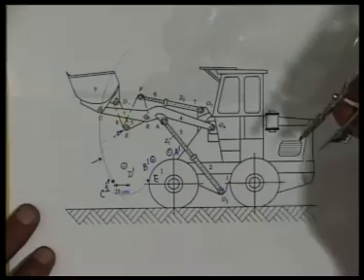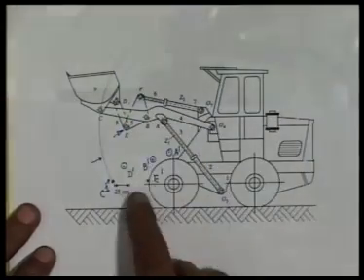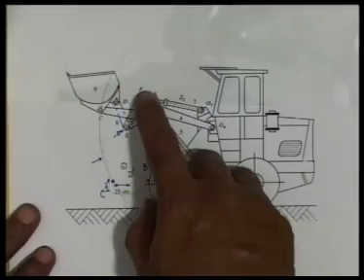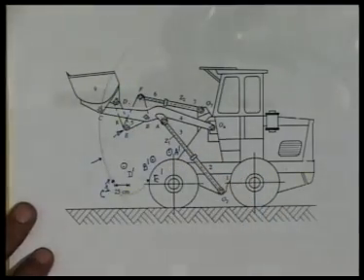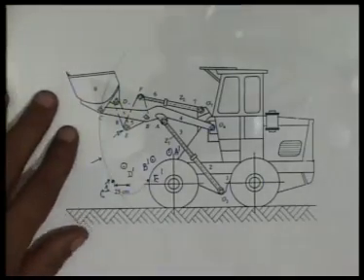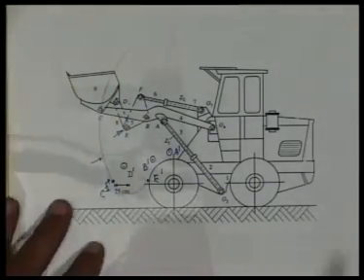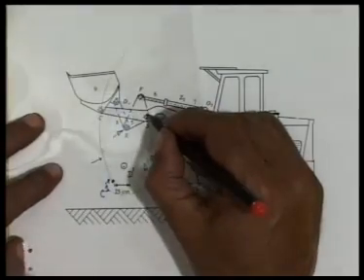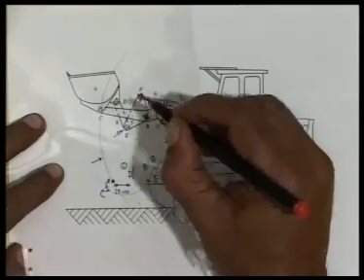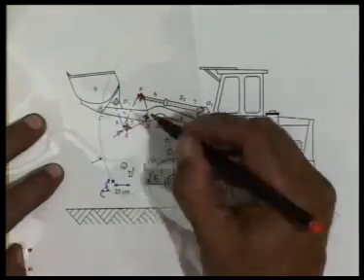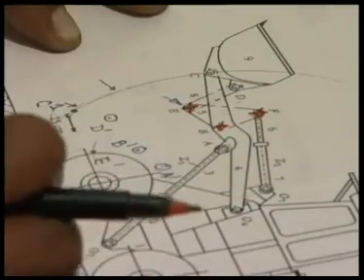Similarly, to determine F, I know the locations B, E and F. These are the 3 points on the same rigid link 5. So I can again use this tracing paper as an overlay and mark B, F and E. Their relative positions do not change, and I know where B and E have gone.